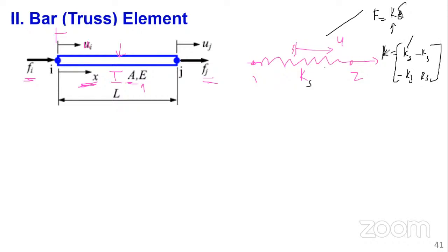But the K out here, the capital K, if you put it in brackets, is a stiffness matrix. The KS for the spring is just the stiffness of the individual spring. But now we are talking of an element with two nodes, node 1 and node 2. We are talking of a 1D two-node element. That's why we talk of a stiffness matrix, which encompasses behavior at both nodes, Ui, Uj. So don't confuse this K out there and the K's that we talk of inside the matrix.